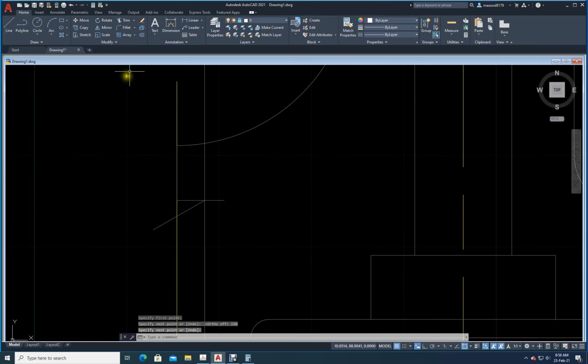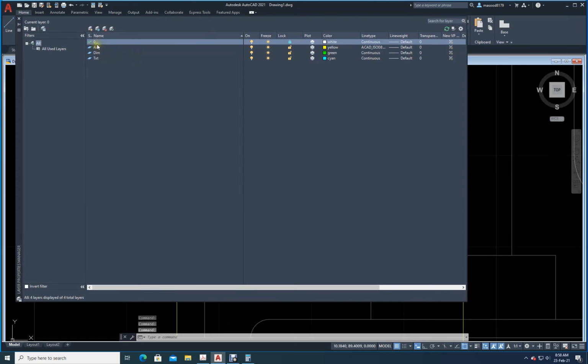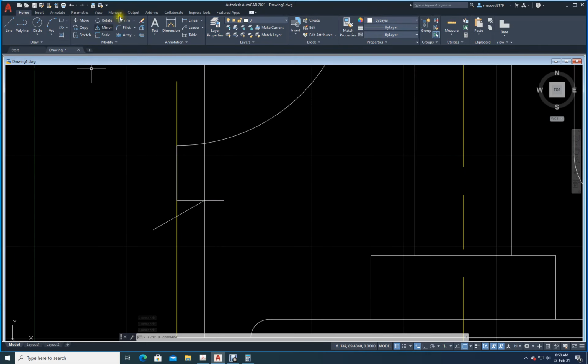So now whatever extra is there, I will just remove it. Go to trim command. Do you need this? Why is it not there? What's the matter? Let me draw a line. Did I lock? Oh, the layer is locked here by mistake. Let me open it. See the layer. Where is that zero layer? By mistake I have locked it. Okay, let me unlock it. Now I can work on this one. If the layer is locked, you cannot do anything on it.